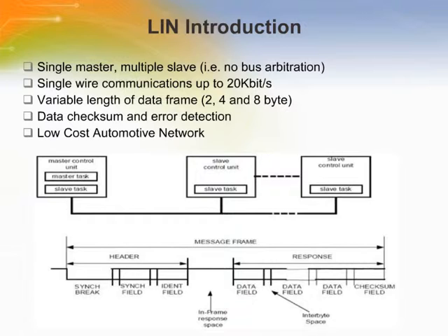The LIN protocol is mainly intended to support the control of mechatronic elements found in distributed systems for motor vehicle applications, but of course it can be applied in many other fields. The LIN protocol concept is a multiplex communication system whose level and associated performance are clearly positioned below what we can expect from a CAN controller area network. It is very different from and much simpler than CAN. It is even simpler than the I2C bus, being based on the concept of a subnetwork containing only one master with a finite set of slave nodes.